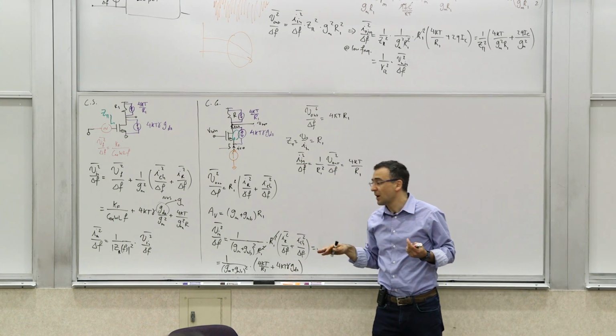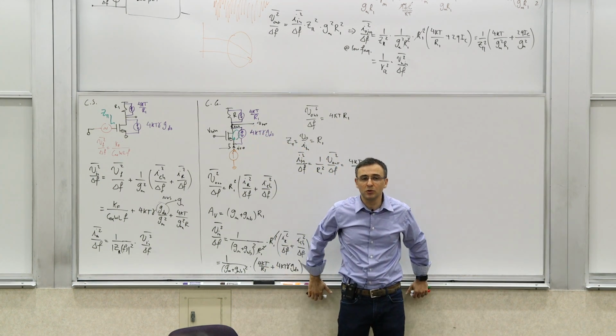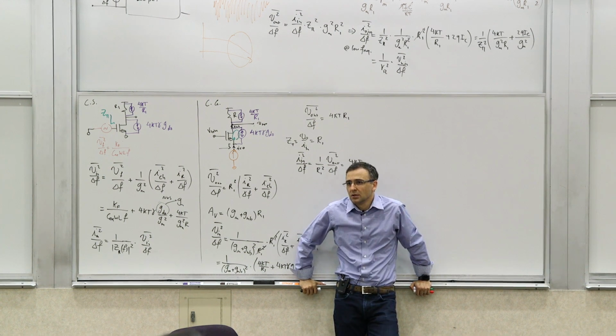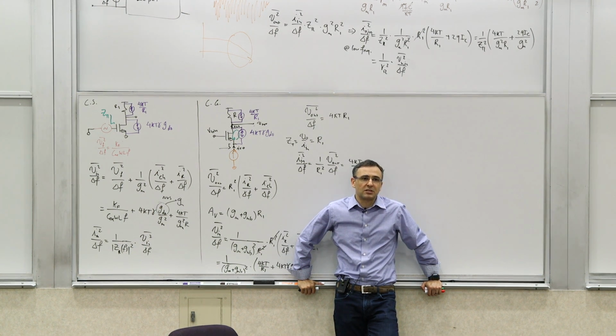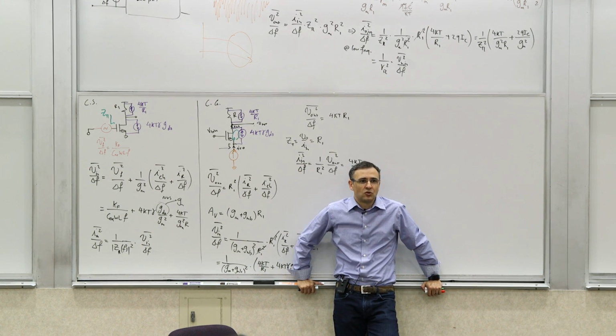And a couple of observations. First of all, the fact that whatever current noise you have at your output is directly appearing at your input because your current gain is 1, right? Is it a good thing or a bad thing? It's a bad thing, right? Because you don't get any reduction. So whatever you have at the output of this stage will appear at its input as current noise. So when you're dealing with a common gate stage, you usually have to worry a lot of times about the current noise, because that noise just directly appears at the input. There's no attenuation of that.